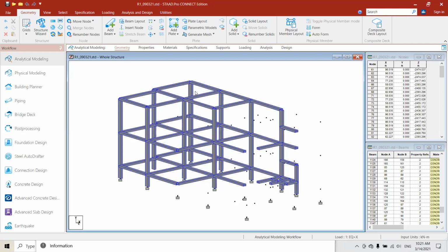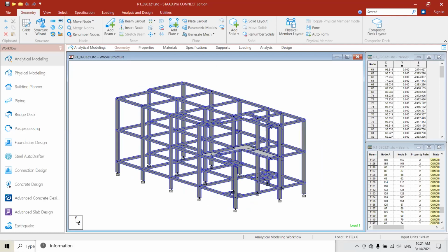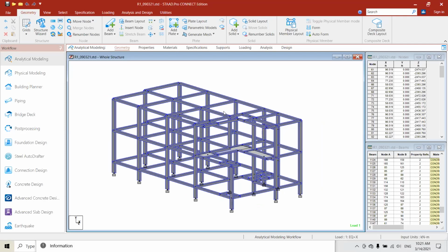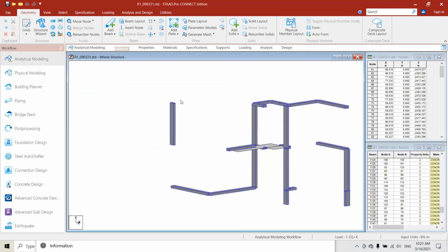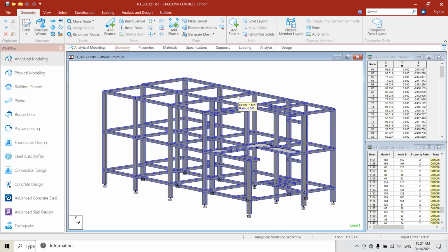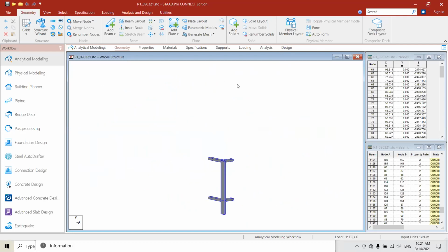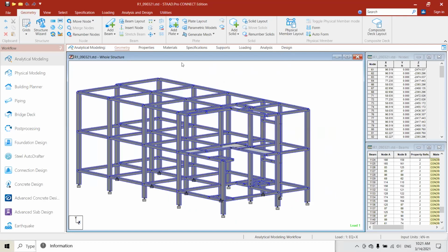So you can see this is our structural system, and the project was already finished, and all the work was done by my students. This is a factory building, where we need to take so many clauses and follow all the Indian standard codes, like what is the live load, what is the dead load, and all the loads will be taken as per the Indian standard codes, like IS 456, IS 13920, IS 1893, and IS 875 part 1 or 2.